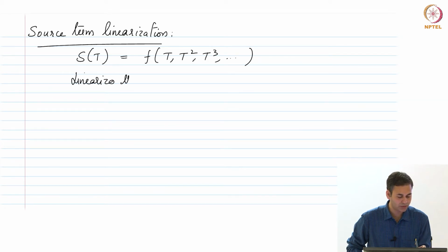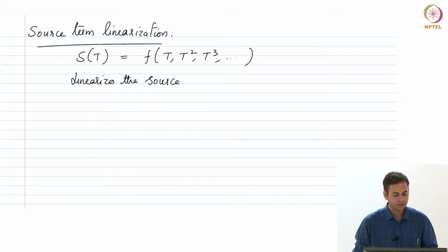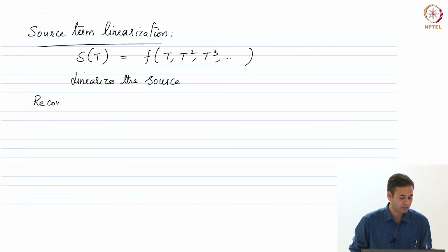linearize the source because our nominally linear framework would only allow a linear model for the source terms. Also, having a linear dependency on the dependent variable, the temperature, is much better than having a constant in terms of convergence. Because of these two constraints and motivations, we linearize a source term. There are several ways to linearize the term, whereas the recommended one is using Taylor series expansion.